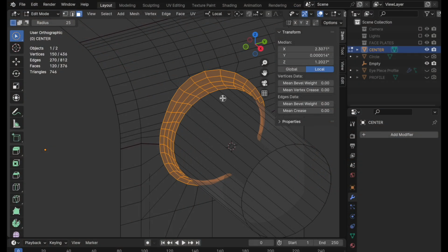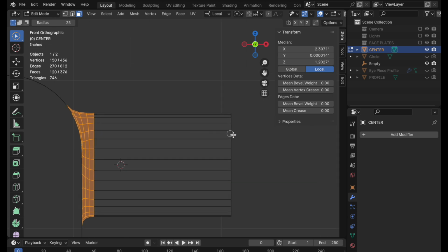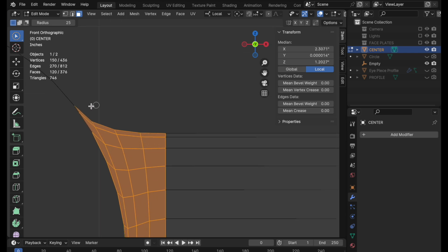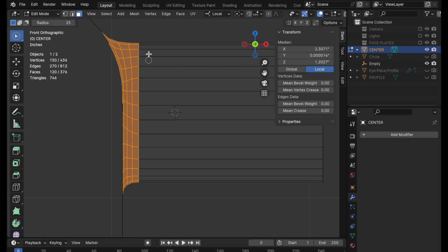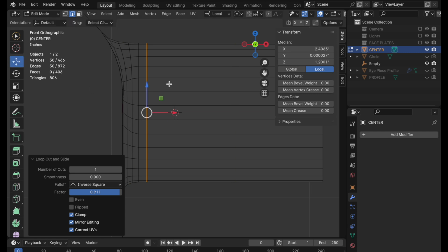We need to add a couple of boundary loops in. If we take a look at this in the front, along this long shaft, we want it to be flat, and we have curved polygons coming into that. So we need to add a boundary loop about right here. So we're just going to add that right there. And let's come over and just automatically set the crease weight to 1, and that will prevent subdivided polygons from